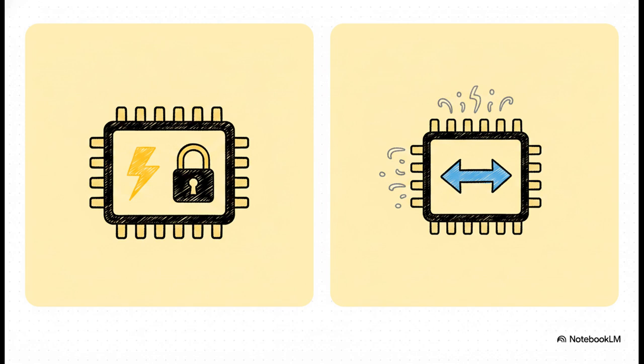Then on the other side, you've got SRAM. This is your volatile RAM, the read and write space where your initialized variables in the .data section and your uninitialized ones in .bss hang out.